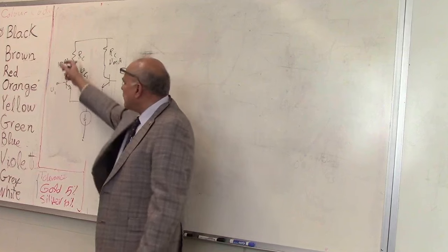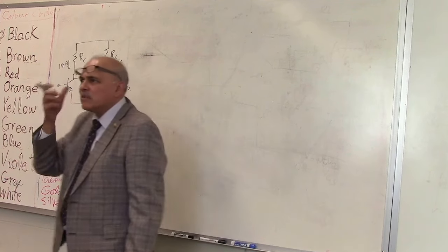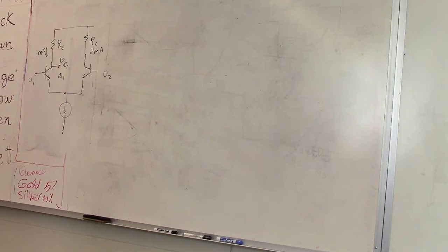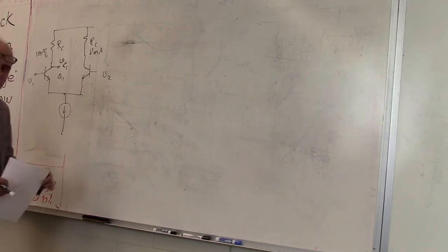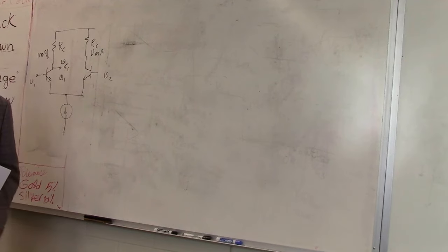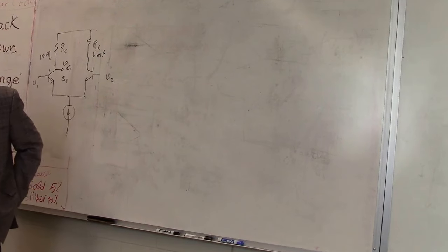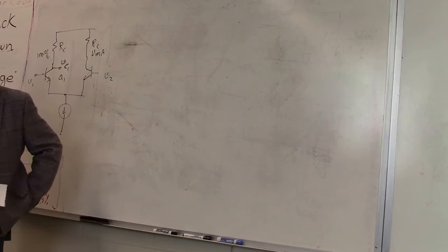So in the big picture, we can just assume that the collector current and the emitter currents are equal because the base current is so tiny that it probably makes no difference. It makes a difference for something called a power transistor, but these are not power transistors. Okay? So later on, if you do power electronics, your betas will be closer to 25, but here they will be closer to 150. So you can ignore that.